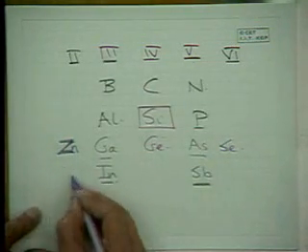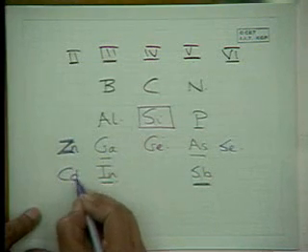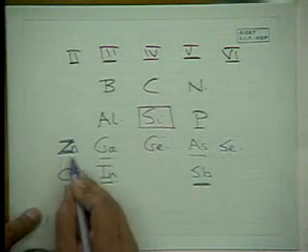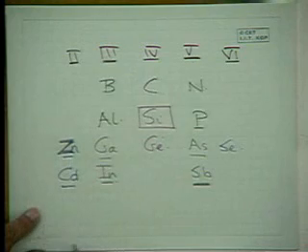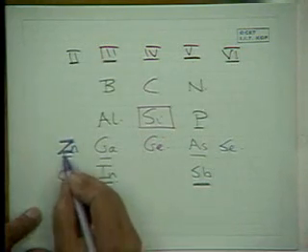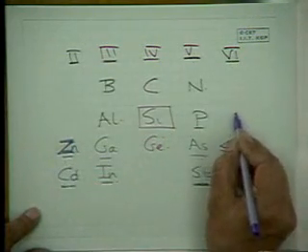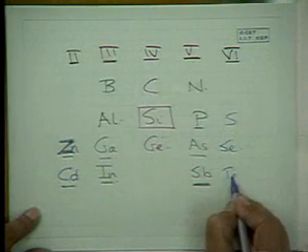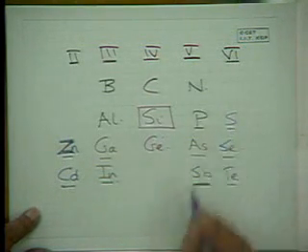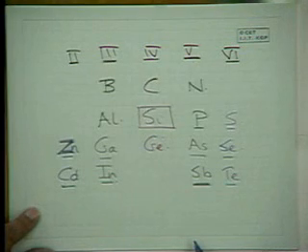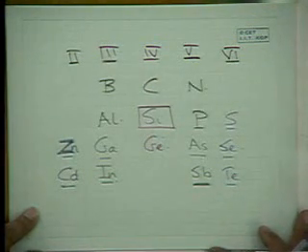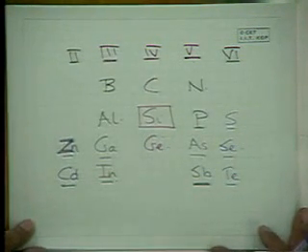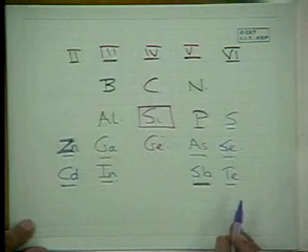The 2-6 compounds are based on the zinc and cadmium families, which combine with the chalcogenides sulfur, selenium and tellurium to yield wide band gap semiconductors, which are important for devices such as blue emitting devices.